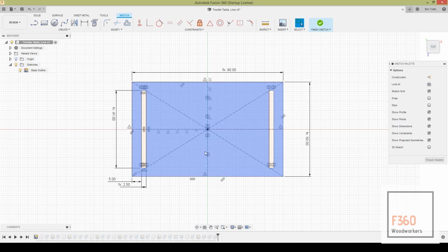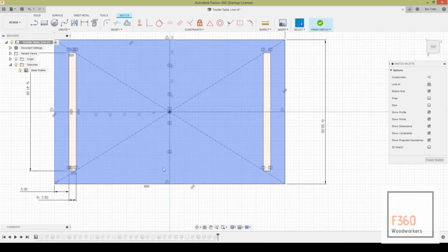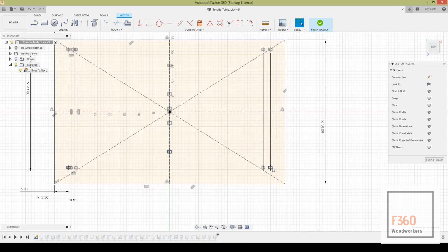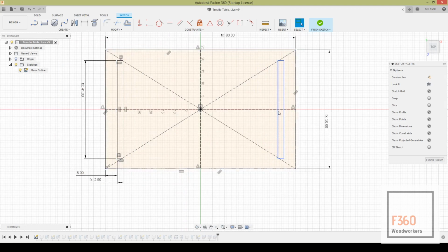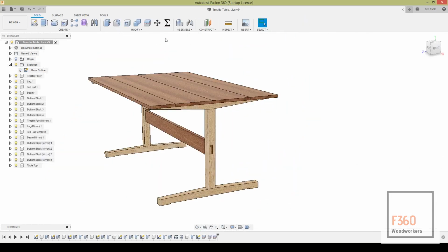So let me show you an example. I have the symmetry sketch constraints applied. I'm just going to delete them. Okay, so now this rectangle right here, you can see it's turned blue. It no longer consists of black lines, which means it is unconstrained, which means whenever I update my model, the design intent will be lost and my model will look goofy. And nothing happened yet because I didn't change any of my dimensions.